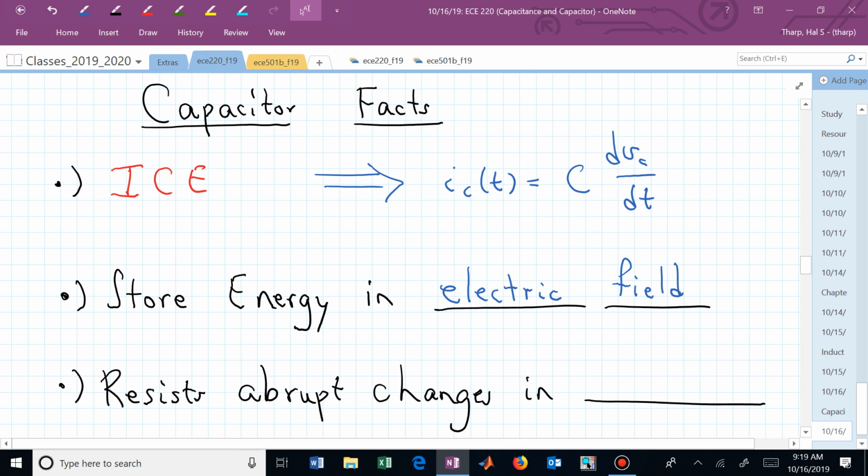Infinity is 5 time constants, roughly. And a time constant can be very short. So going to infinity and back doesn't take that long. We don't have to be that patient in electrical and computer engineering, because 5 time constants could be fractions of a second. Where was that from?